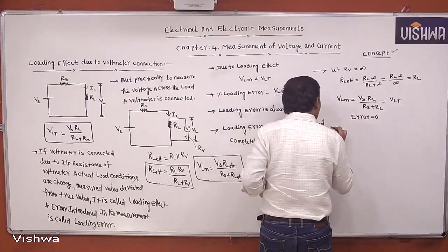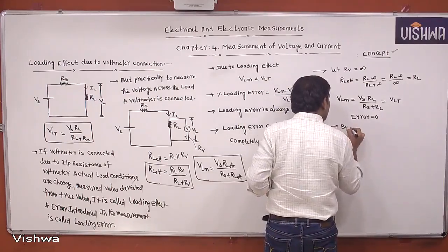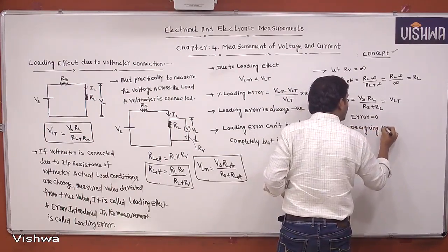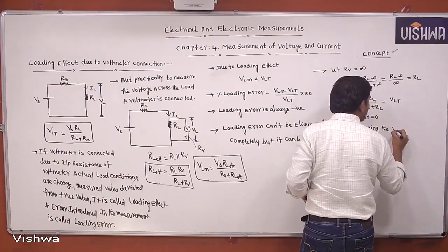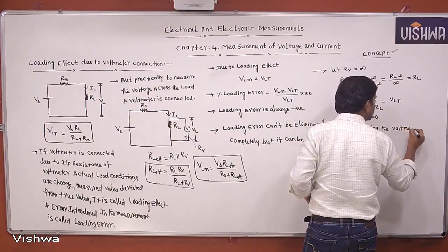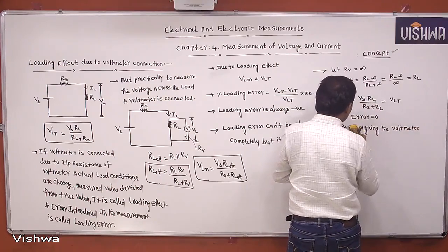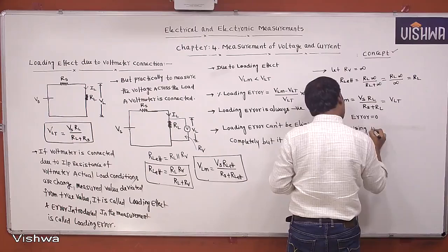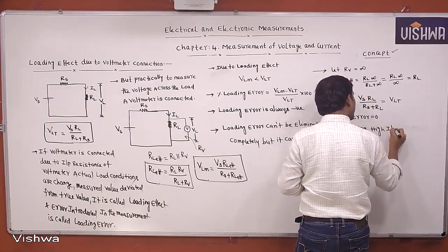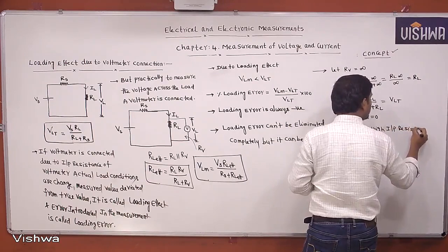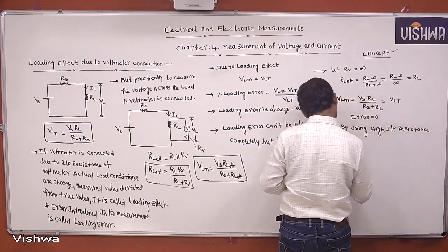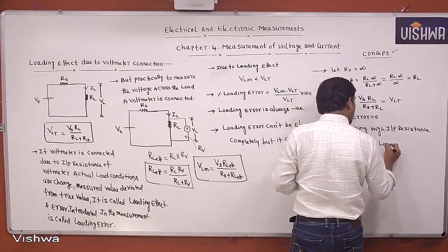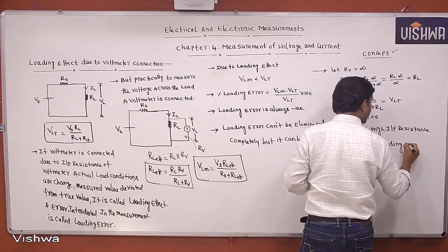Therefore, by designing the voltmeter with high input resistance, or by using a high input resistance voltmeter, the loading effect is reduced.